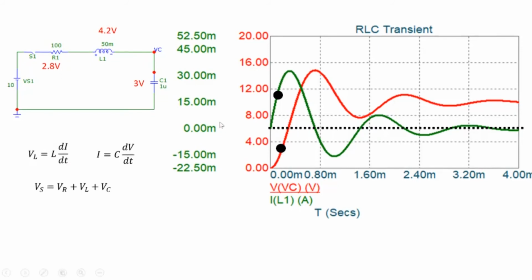Okay, so we are here at this particular point. The capacitor has charged somewhat. The inductor current has risen to some value here. And note the value here. There is a drop across the resistor now. There's a drop across the capacitor now. And the drop across the inductor is less now because KVL must be satisfied. So it's 4.2. And because it's 4.2, the current is now no longer increasing as sharply as it was at time t equal to 0. So the curve is bending.